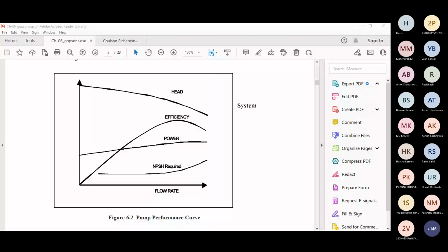Suppose हम डायनामिक पंप में क्या करते हैं, हम वाल्व को थ्रोटल करके फ्लो रेट कंट्रोल करते हैं, राइट? वी आर नॉट चेंजिंग द आरपीएम ऑफ द पंप, राइट? सो बेसिकली पीडी पंप में आप at a particular stroke length, स्ट्रोक पे आप फ्लो रेट चेंज नहीं कर सकते. That's why it is called a constant flow rate pump. Clear?